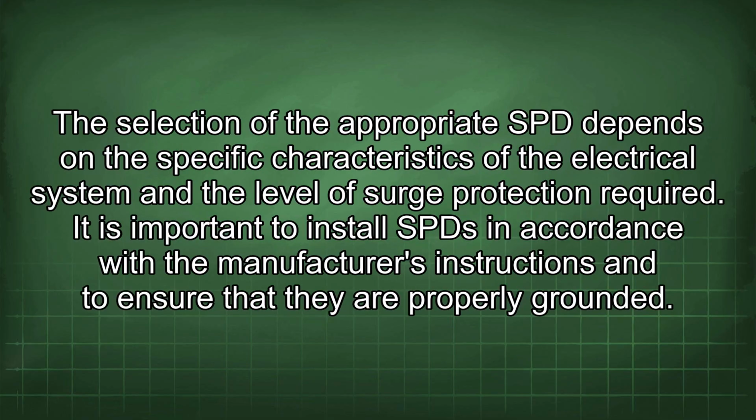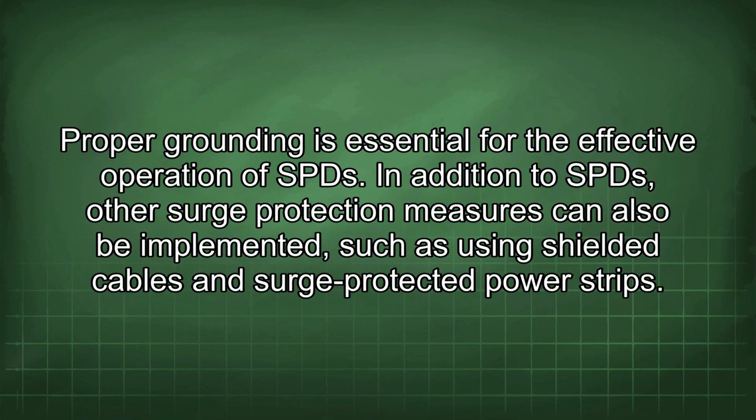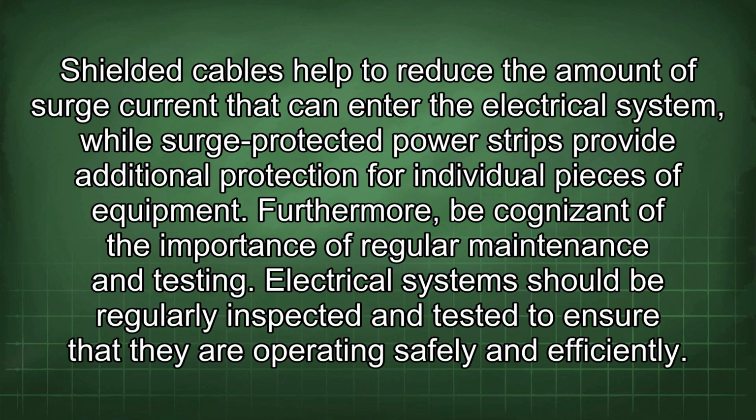The selection of the appropriate SPD depends on the specific characteristics of the electrical system and the level of surge protection required. It is important to install SPDs in accordance with the manufacturer's instructions and to ensure that they are properly grounded. Proper grounding is essential for the effective operation of SPDs. In addition to SPDs, other surge protection measures can also be implemented, such as using shielded cables and surge-protected power strips. Shielded cables help to reduce the amount of surge current that can enter the electrical system, while surge-protected power strips provide additional protection for individual pieces of equipment.